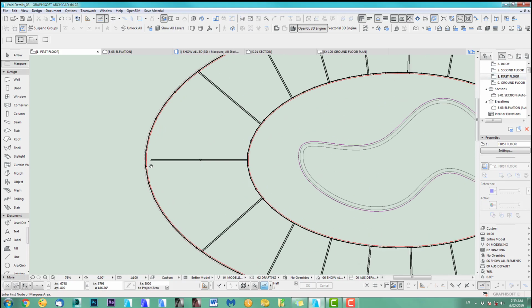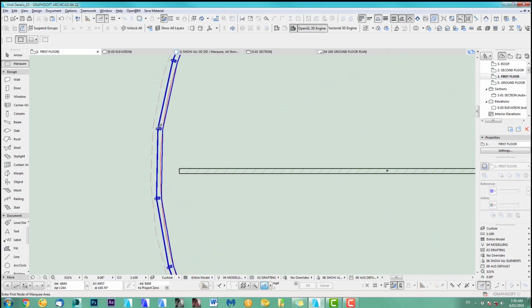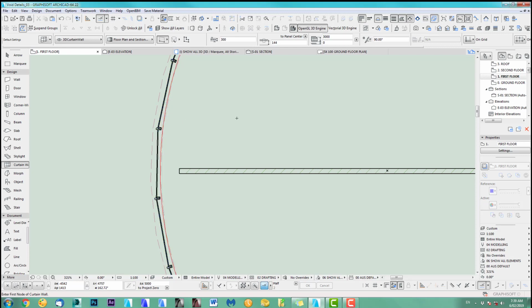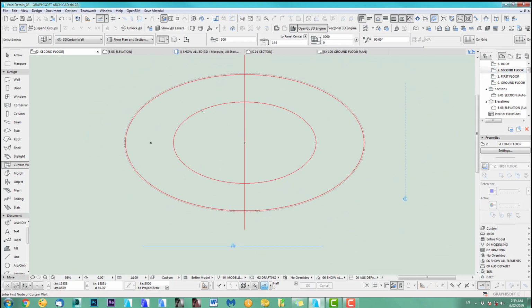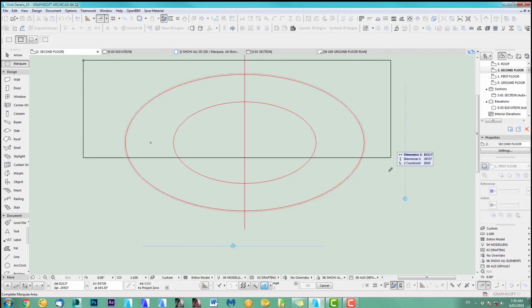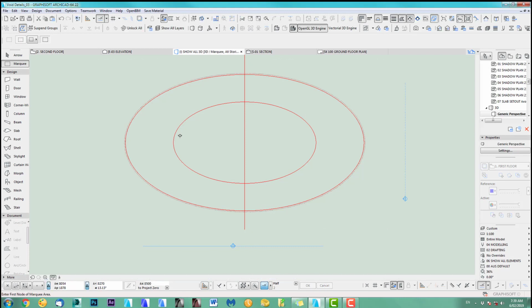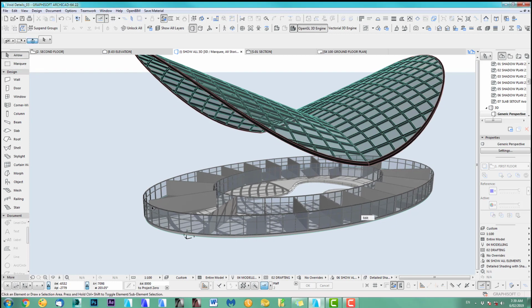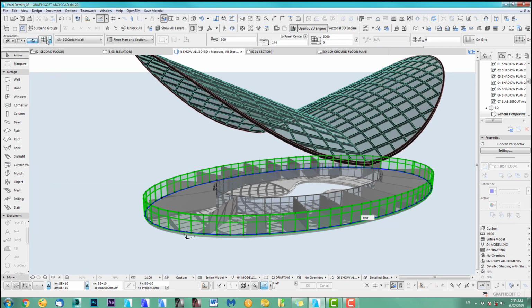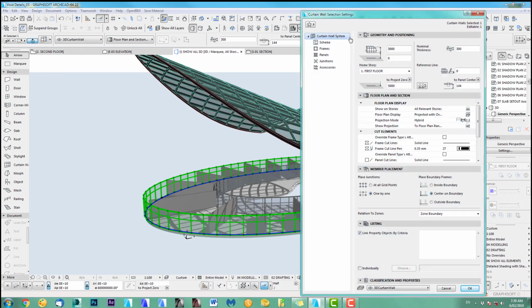I go down to the first floor and I would think I like to pick those ones. So I'll just use that tool, Alt click on the PC and we go back up and we create some more of those curtain walls, or you can just extend them if you want to. So let's do this. There's always a couple of ways to work in ARCHICAD. So what you can do is you can just take this one and we extend this up here.